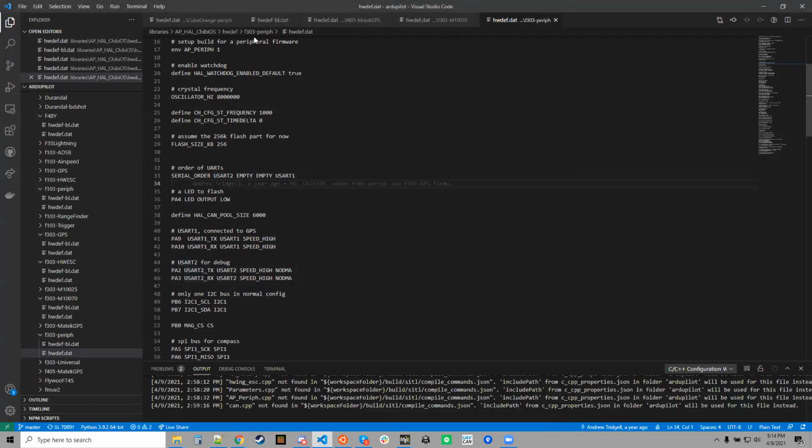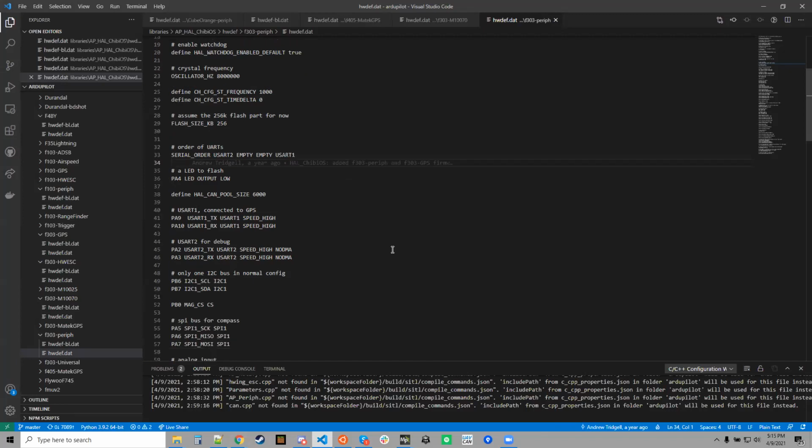So this particular device, for the basic one, it's COM 1 and COM 4 is available. So it'd be serial ones. I'm sorry, not COM, serial 1 and serial. Oh no, I'm sorry. This is serial 0 on this one. So serial 1 and 2 are not available. The first one's for the GPS. Typically, the defaults are your first one's your debug port. Serial 1 and 2 is your telemetry 1 and 2, and then the next one would be GPS. So this particular target uses that as a default, just so the rest of the library kind of uses it. All the defaults kind of line up.